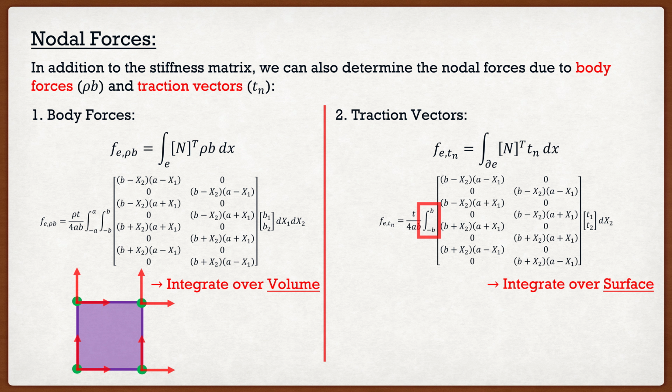So you guys may be saying, Clayton, what exactly are we doing here? Well, it's kind of the same process as before with the body forces. If I have a distributed load acting on my element, we can see that a lot of that load is acting on the side of the element and not the node itself. So what we're going to do is take that distributed load, which again acts over the surface of our element, and convert it to an equivalent nodal load.